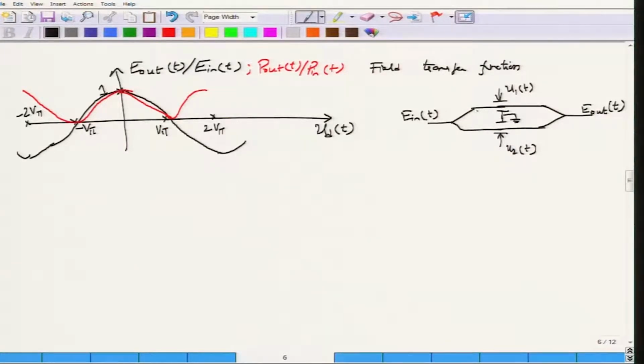Now, as the upper portion of the light passes through, let me try and give you a graphical interpretation, hopefully it would be easier to understand. So, this power which is coming in, or this electric field which is input to the modulator, gets split into two parts, both in phase. In our simple model we will consider them to be in phase. Later we will see that in a waveguide construction there has to be a 90-degree phase shift between these two arms. However, that 90-degree phase shift is offset by another 90-degree phase shift at the coupler. Therefore, the overall phase shift will be 180.